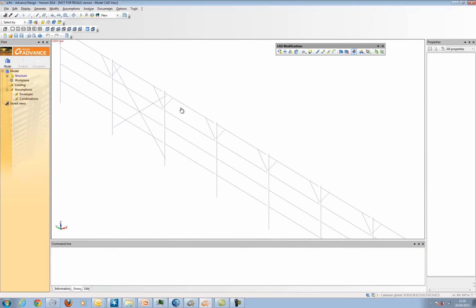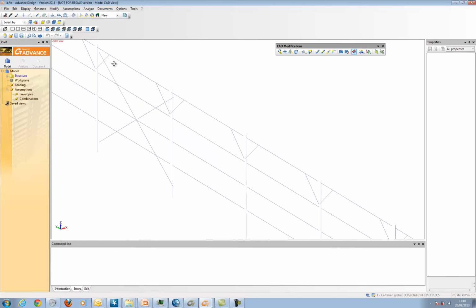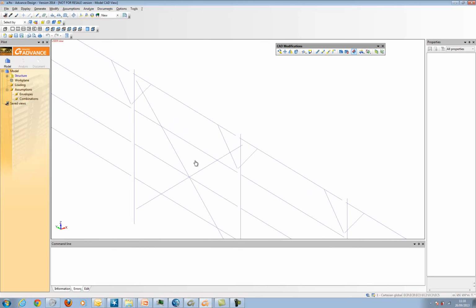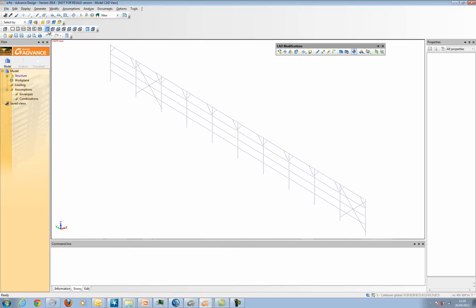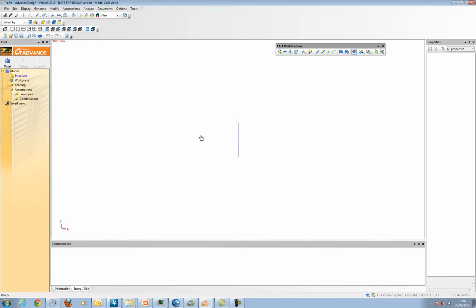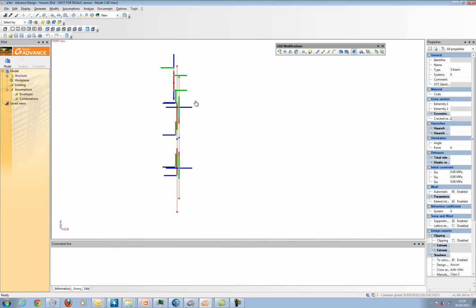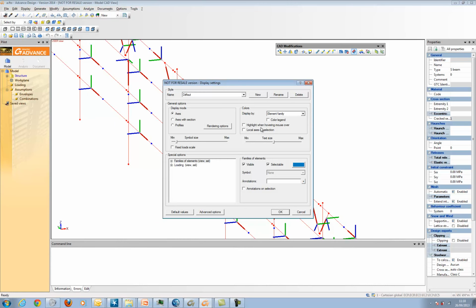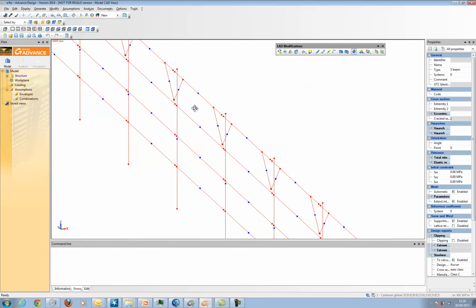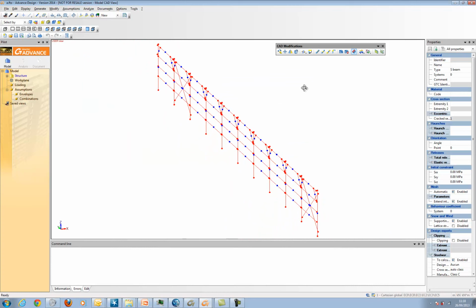So we'll obviously have to trim or extend some elements here, but before we do that, we should make sure that they all belong in the same plane, because actually they don't. So the first step will be using the projection on plane function.